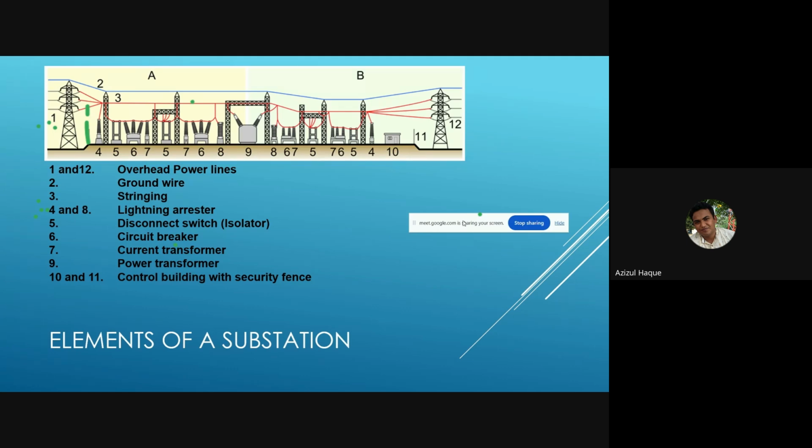They are basically transmission substations, used when a bulk amount of power has to be transferred. Then 765 kV is more suitable than a 400 kV substation. So this is basically decided depending upon the quantum of power.